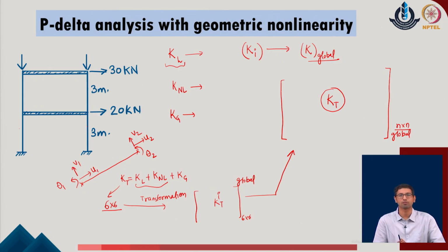matrix can be evaluated. What you need other than the regular linear stiffness, which was done in the previous problems, is only the contribution of the nonlinear and the geometrical stiffness terms of the given system. But we need to be a little careful that these terms of the nonlinear and the geometrical stiffness parameters are not going to be constant values, but rather they are themselves functions of the displacement terms. So, assembly of them as well as general derivation of them require some additional steps in the given system, which we discussed in the previous lectures.